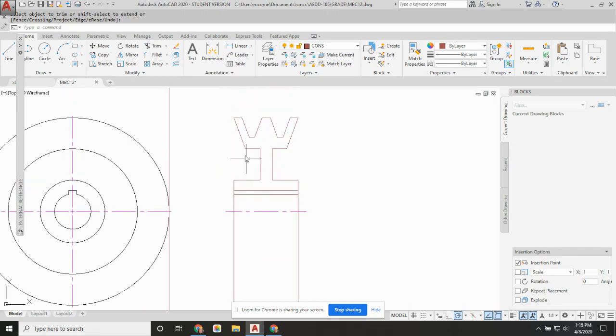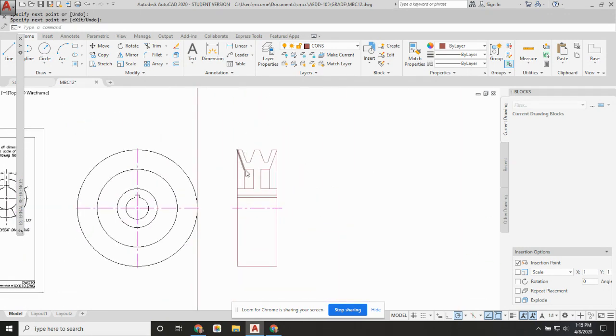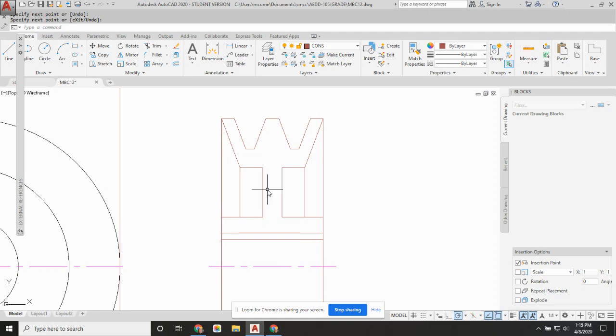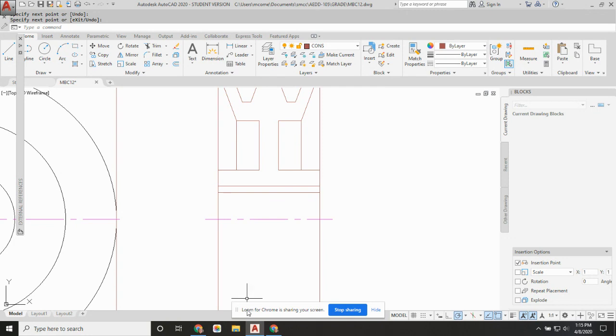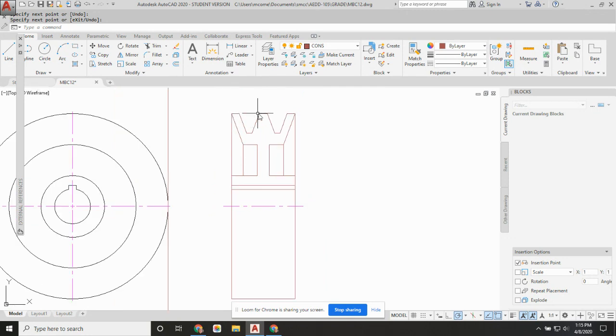So on this half of the drawing, and by the way, these lines actually need to be put back in as object lines here because we would see them beyond. And we'd also see some object lines here for the edge of that pulley. The inside edge of that pulley would continue and show up as an object line beyond. But from here down, we're going to see all the lines that would be created as exterior object lines from these objects. So I'm going to switch to the, I'm also going to mirror this V pattern to the other side of the drawing.